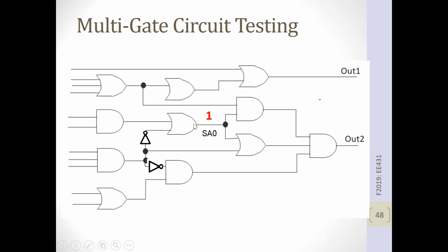And if it's wrong, it will be a 0. And remember, with circuits, if you have them in a chip, all you can do is set inputs and watch outputs. So this 1, if it's actually a 0, where you set this wire to 1 but it ends up showing up as a 0, that has to somehow propagate through this AND gate or through this OR gate and out to out 2. So you can say, hey, that node is not behaving correctly, or is behaving correctly.